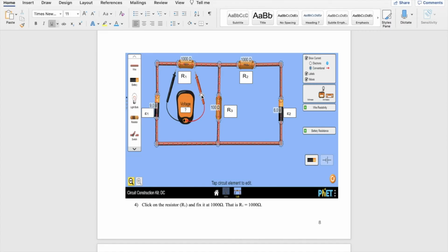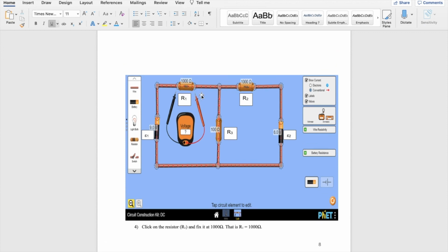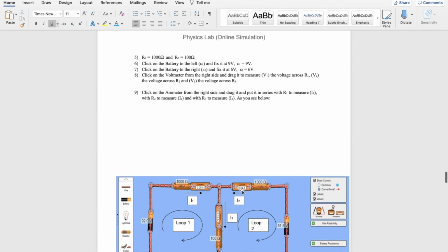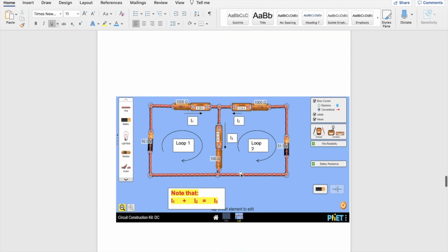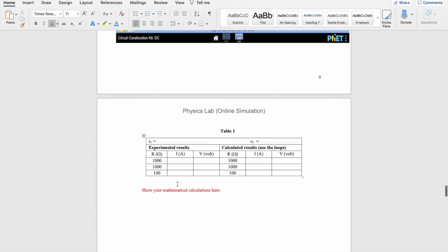So here are two ways you can do. You can find the voltage and current. You'll have to do both. First is the experimental way. So once you complete a circuit like this, take your voltmeter, multimeter, and measure all the voltages and currents across the resistor or in its sections. Okay, by using these voltmeter and ammeter, you are doing the experimental way, and you can verify your junction rule and the loop rule based on the experimental data.